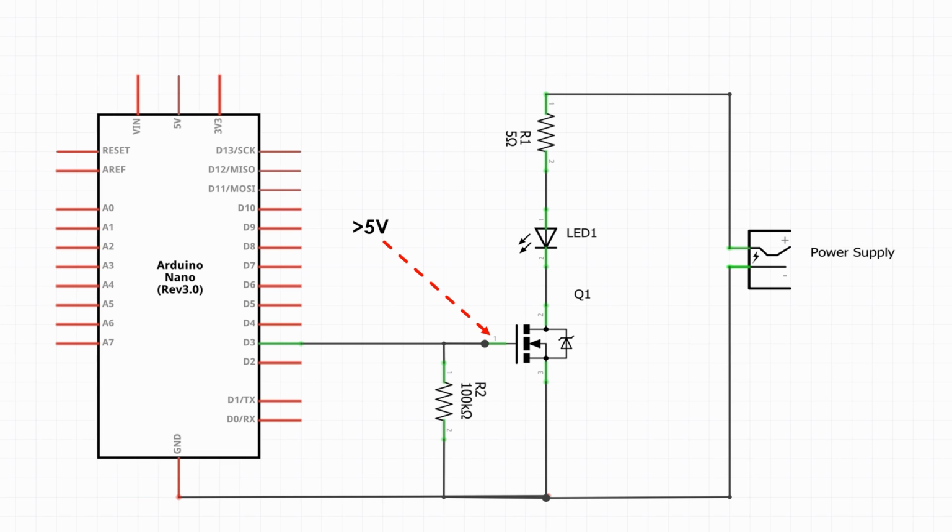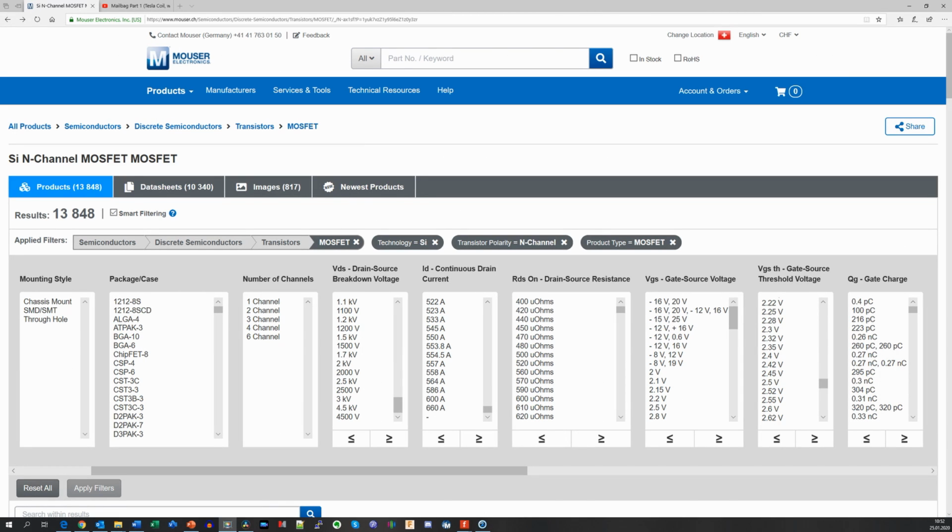These transistors cannot be used with our Arduino projects, even more with 3.3 volt ESPs. Here we have to have a sharp eye to find the right ones. But how can we find them? Sometimes they are called logic level MOSFETs. This is an indication. And we can try to select VGS threshold voltage of less than, let's say, 2.5 volts